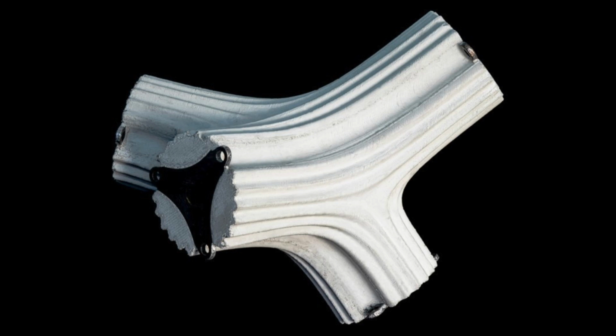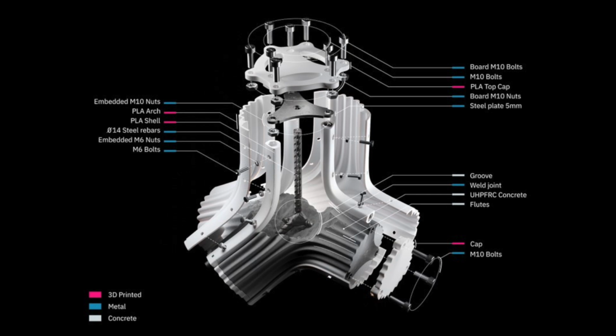And what is interesting for me is that all the features that are visible here are actually telling a little bit of the story of how the formwork was working. So you see the grooves that are following the direction of the holes for the bolts and the nuts. They are the arches that we saw in the first picture holding together the plates. And the corrugated surface is actually coming from the reinforced shell that we were using. And this is the formwork in this view, where you see all the different parts that work together.